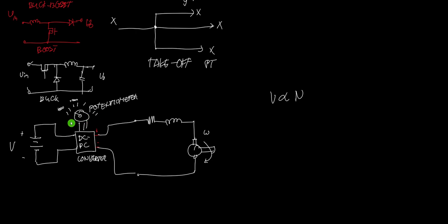So if I just adjust this one into 1000 RPM based on the scale, the problem is, is it really 1000 RPM? Is it the angular speed of the DC motor, is it really 1000 RPM? How can you say that it's really 1000 RPM? So this is an open loop. This is the problem of an open loop system because the input doesn't care about the output. We don't look at the output.